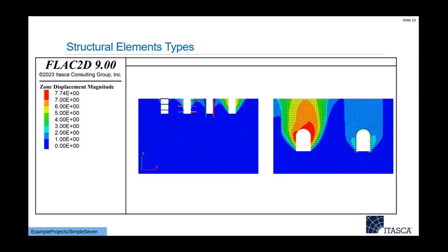And this is a side note. I just created 2 models. These aren't 2 separate programs that I'm putting together in one picture. These are actually 2 different models, separated, but you can do that exact thing as long as your boundary conditions are set. It's an easy way to run multiple models without running the program twice.